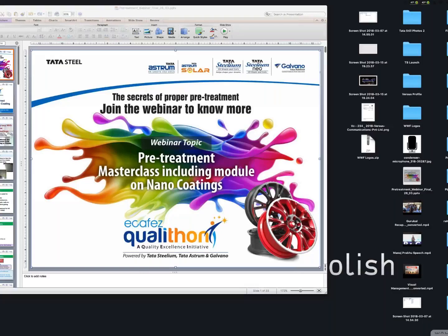But this silicon, if it is embedded well into aluminium, there should not be any problem. But sometimes in case of aluminium, when it is welded, especially the aluminium radiators, this particular silicon floats on the welds, and then they create an adhesion problem. But you cannot do anything with pre-treatment on that. You cannot remove that silicon with pre-treatment.